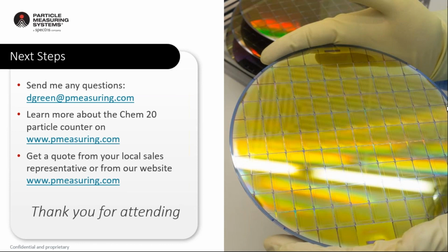It may be sufficient to give you an approximate idea of how long the filter flushing may take, but the cleanliness of filters is likely to be quite variable. So in order to be absolutely certain and have confidence that the filter is sufficiently clean before it's used in production, it would be highly recommended to measure the cleanup curve for each individual filter.